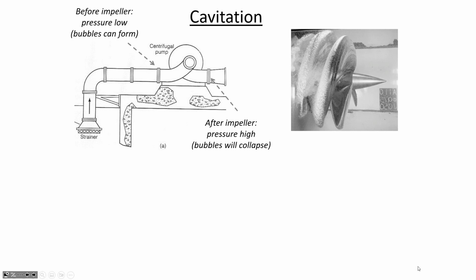Did I show you some pictures of a dam in California that was all broken up? Okay. They had low pressure at the bottom of the spillway because as the water went down that spillway, the velocity got really high. So there was a section of water in contact with the spillway that had a high velocity and therefore low pressure.